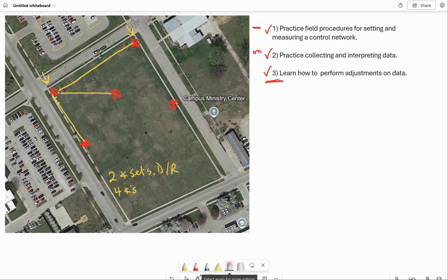You're going to tear down and move forward. So you're set up here. Now you're backsighting here. We're going to foresight to our next forward control point. And while you're set up like this, if you want to go ahead after you've turned this one in, turn in a set of angles to that one, you've now completed the requirement for the 2 measurements on the interior point. So you will tear down, move forward, occupy, backsight. We're going to turn this point in.